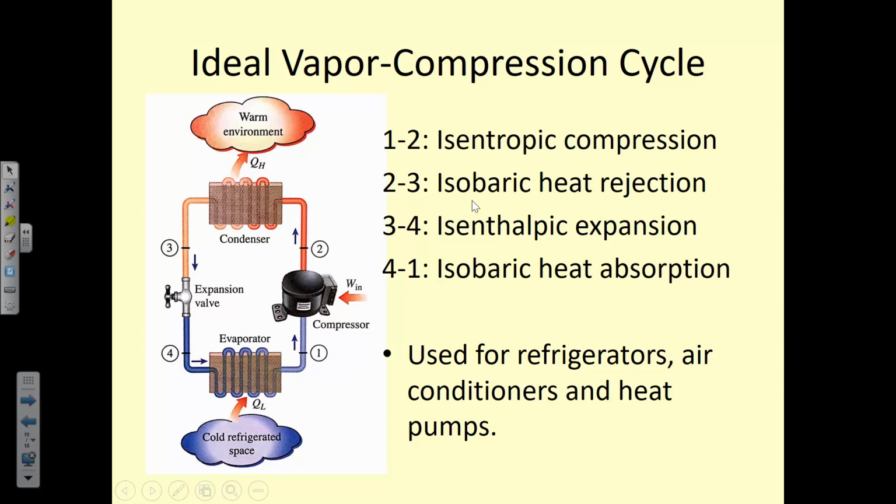If you were to go to your home and look at your heat pump outside, you would see these various components. The compressor is usually just right there outside. The evaporator and the condenser, they switch. Whether you're using it in the fall or the summer, the evaporator becomes the condenser and the condenser becomes the evaporator. So it's all in that nice little area right outside. The expansion valve sometimes is inside.